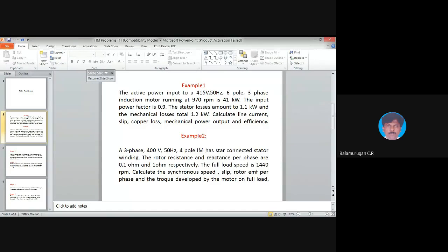So what are the voltages here we are having? We are having this voltage as 400 volt. This is the input voltage. We can consider this as E1. Okay. So what is the connection on the rotor circuit? It is almost similar to star connected and it is short circuited. So that is a line voltage. You are supposed to calculate the phase voltage.